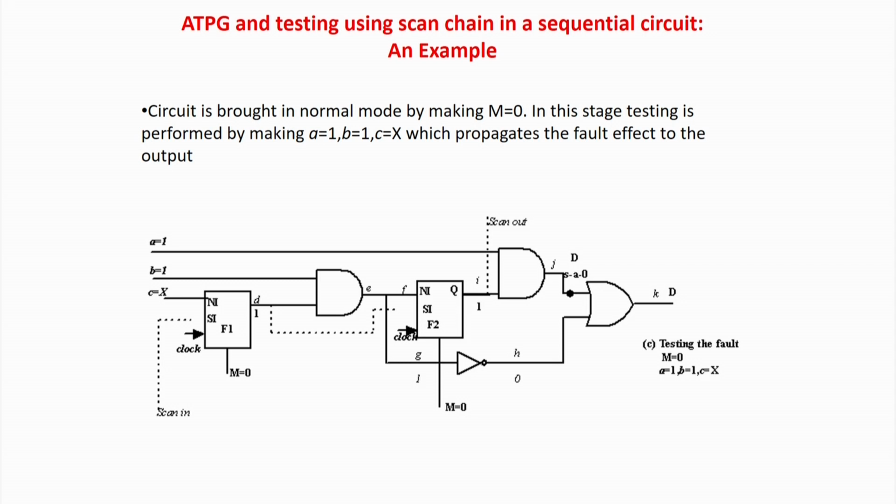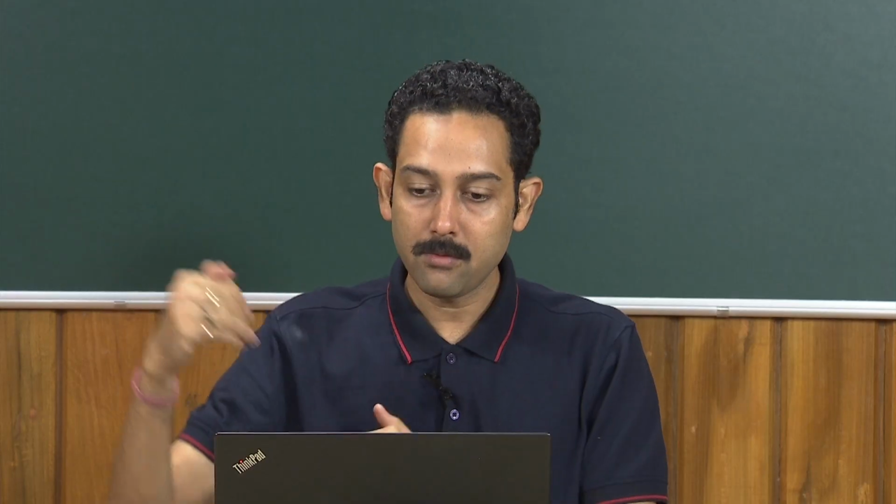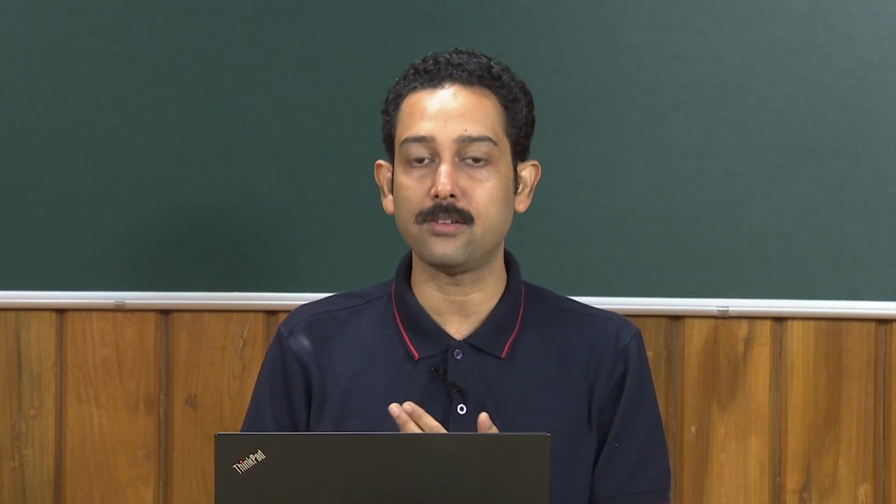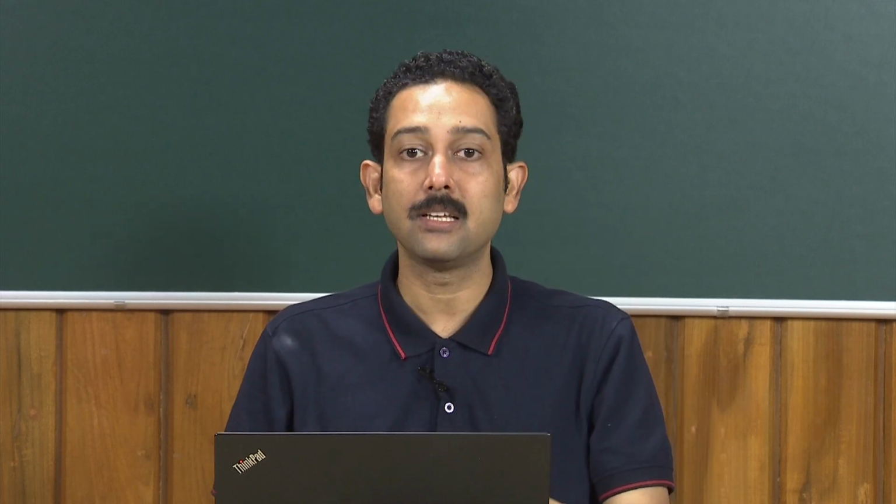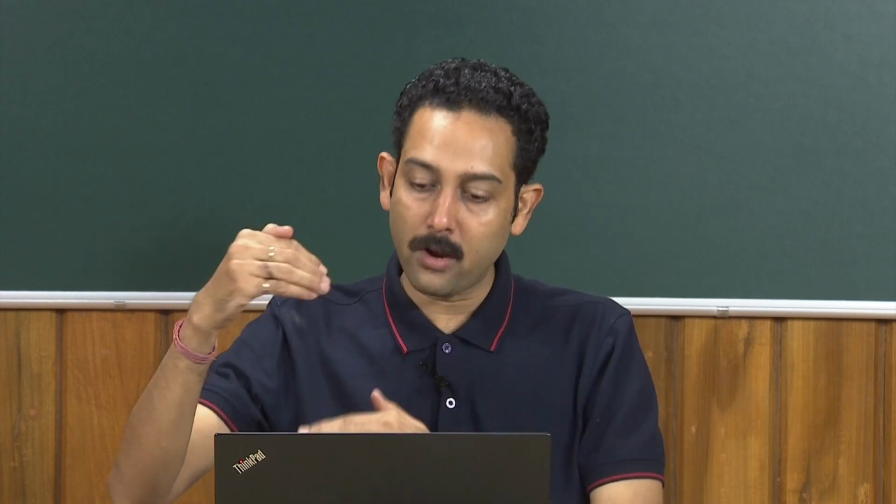So basically what we are going to see is what optimizations can be done with high level synthesis for very complex circuits like NOCs and SOCs. Can I have a very abstract fault model? Can I do the testing at a much higher level of abstraction, at the block level? At the same time, how can I reduce the number of test patterns? This RTL or high level test pattern problem is very recent, but before that people tried to optimize how to bring down the number of test patterns with slight compromise. How can I optimize the number of scan chains so that I have minimum extra pinouts, but still can run the scan chains very fast?